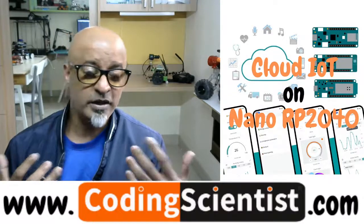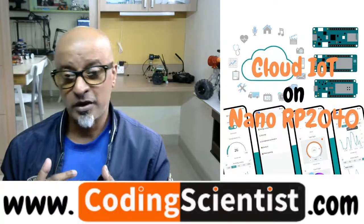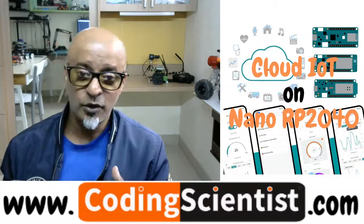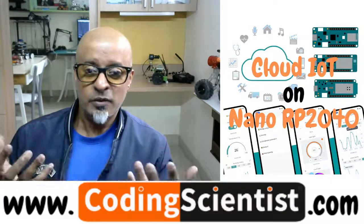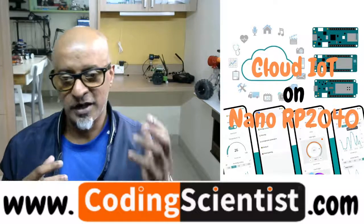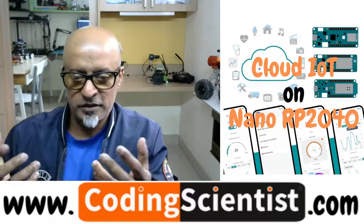It could be either a bug or an older version of the firmware which is not compatible with the Nano RP2040, or some other issue, because as soon as we reset the board using this jumper pin troubleshooting tip you saw on the Arduino site, it works perfectly with the Arduino IDE, but it's not accepting the MicroPython firmware. Once we load the firmware inside and disconnect, it just vanishes.